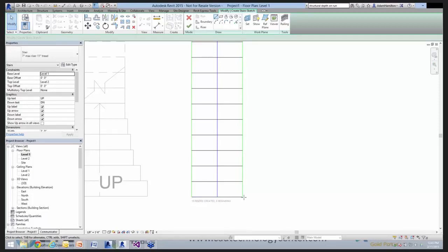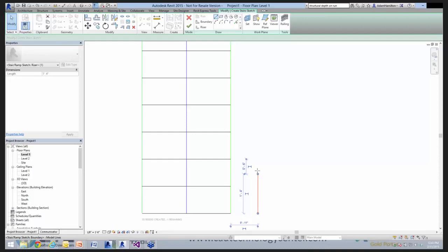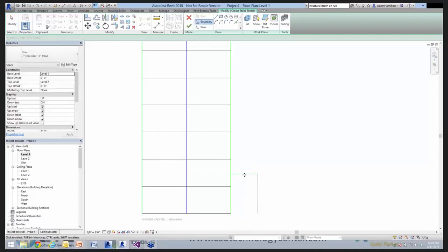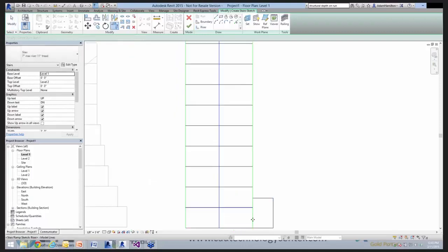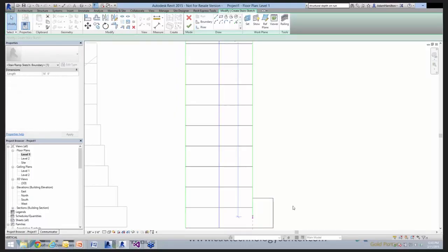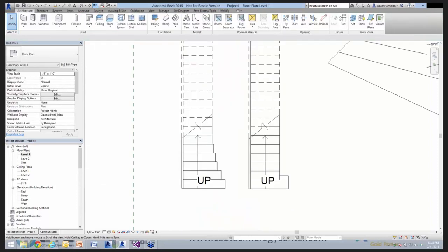Usually I can do this by boundary. Bring this line back, not boundary line, but riser line. And I can pull back this green line, and I can get a wrapped tread.